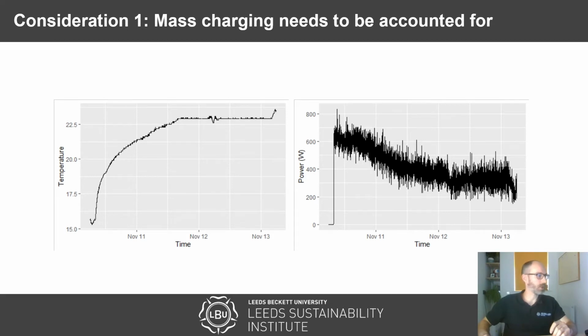Now we can't include these first 2 days of data, as this heat isn't being lost directly, at least, to the external environment. It's just going to heat up the fabric. So these 2 days have to be excluded. But there's no set rule as to how long your building takes to charge up. In fact, we've had big, solid-floored properties in the past that have taken weeks to charge up. So you have to keep an eye on this, if possible measure how your fabric is charging with heat flux plates, and remove the data for this period before analysis.